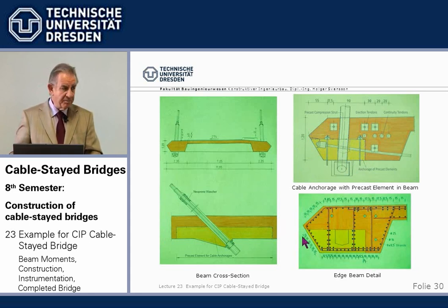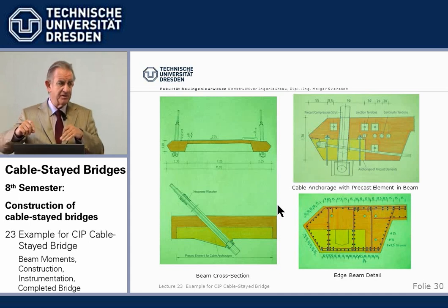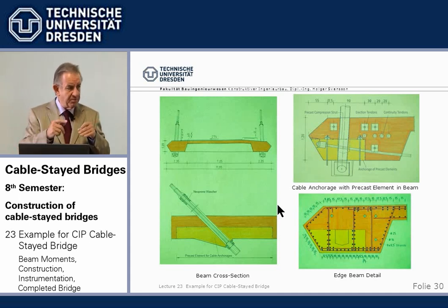And the purpose for that is we wanted to use the final cables also during construction as support of the 12-meter long traveler during casting. We didn't want to use auxiliary tiebacks, which had to elongate it and all that. I explained that to you earlier. So here we found a way, the first time, to use the permanent cables.